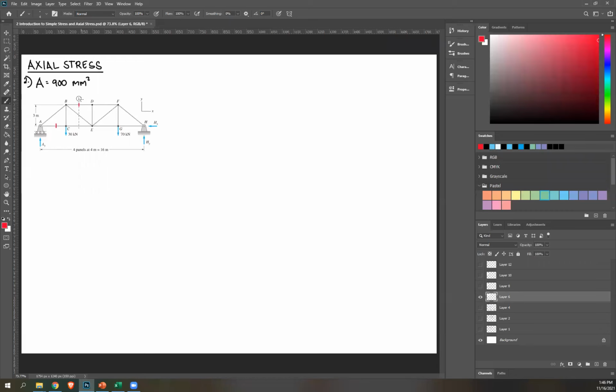Okay. So recall, in order to get stress on an object, I first need its internal force. So what we did in number 1, we cut isolated. Here we have a truss, and we already know how to get internal forces from your truss, right? It's either method of sections or method of joints. So let's say I want to get the internal force in AC first. What should I use, section or joints? Please answer in the chat. Method of sections or joints?